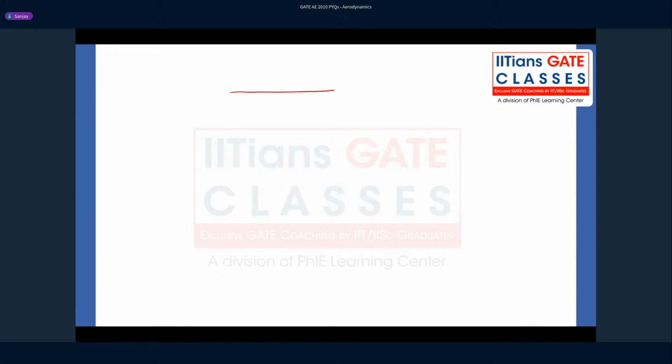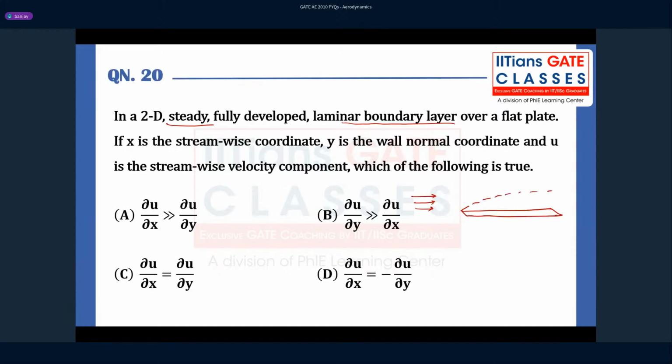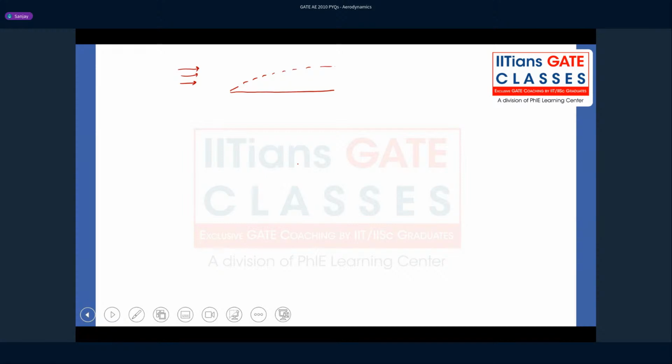So when you have a flat plate boundary layer, you're going to have a thin layer close to the surface where viscous effects are more dominant, right? And they have told you it is a fully developed case. Because it is a fully developed boundary layer, along the streamwise direction you will find that there is no variation in velocity.